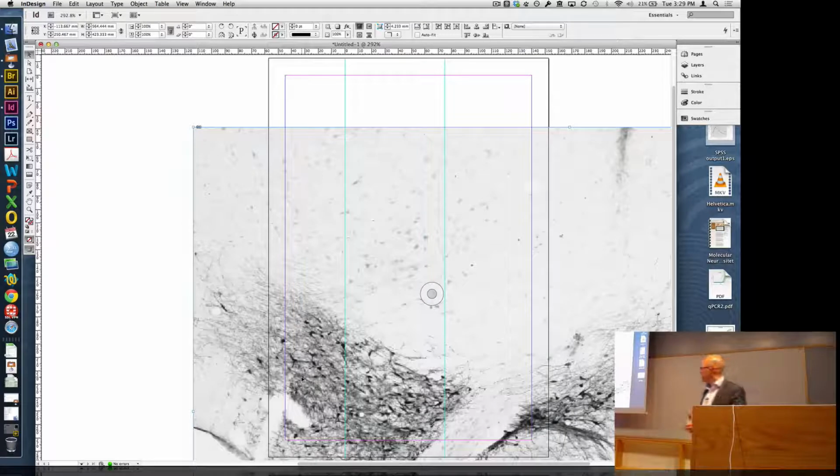One is that this image is huge, and the other one is that it's much worse quality than I saw when I opened this in preview before. So why is the image so low resolution in InDesign? This is actually by design of the software: it brings in a small low resolution image called the proxy image that is just there as a placeholder for you to play around with. But it still has the link to the full resolution image.